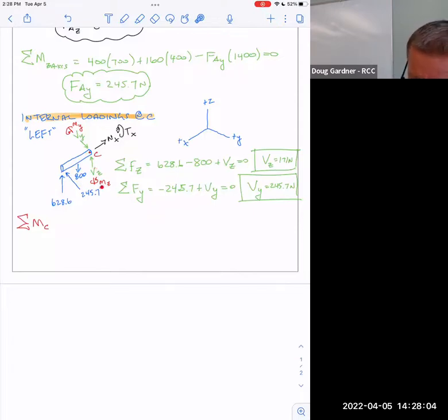So right here is moment Z. There's one of them, so I'll pick that one. You have the force of 625 and the 800. That's right, and that's causing rotation around Y. And that's the reason it's nice to actually write these in. Notice I called that moment around Y and moment around Z, as I should have, and that's what I've got to calculate over here. You don't really have to write the C in this if you don't want to, but those are defined around C. If I move to some different location, it's not going to give the same answers, right?